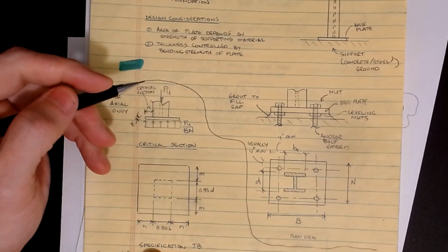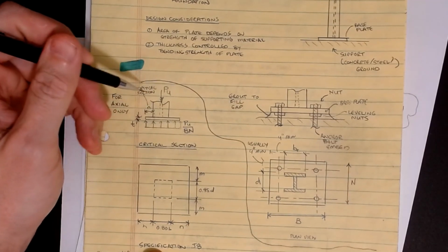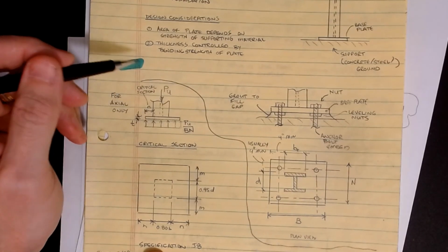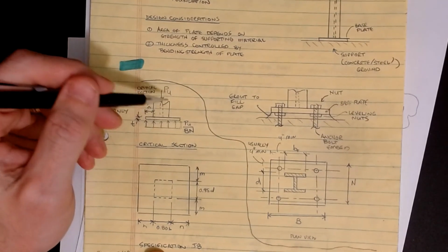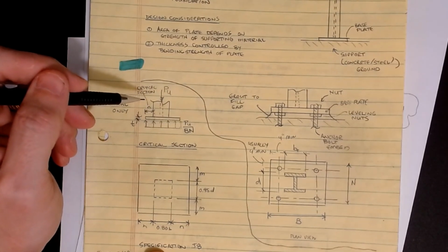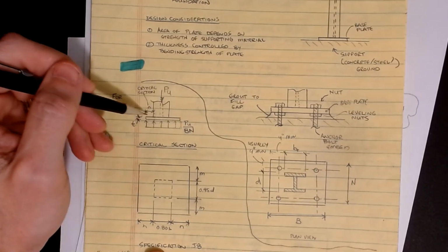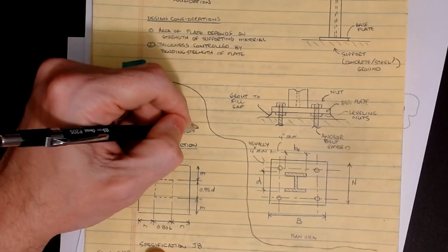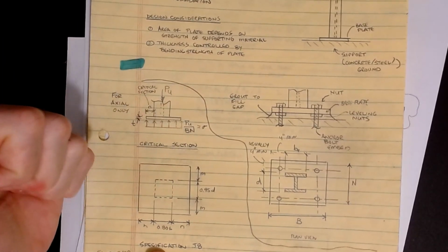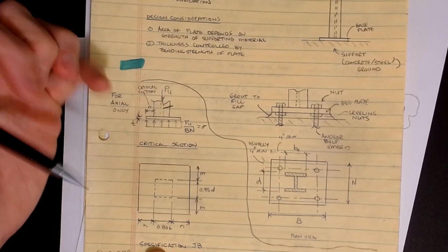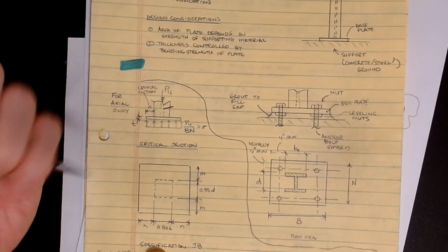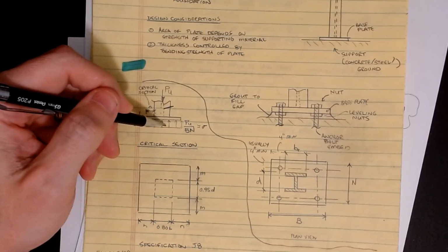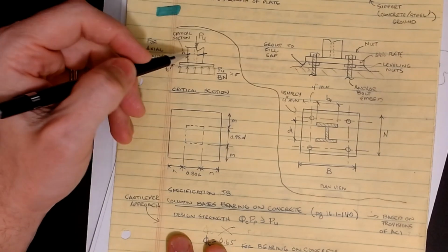Okay, now the way that we design these plates comes from kind of a basic mechanics of materials approach. Now the considerations we're designing this plate for are for axial load only. There's no bending or overturning happening on this. Okay, so if we assume that the plate is centered on the column, then the pressure that's felt by this plate is going to be some sort of normal stress. That's going to be the amount of the factored load divided by B divided by N as we start to calculate that value. And this is what we're going to be comparing to our stress. Okay, so that's how we're going to size for B and N.